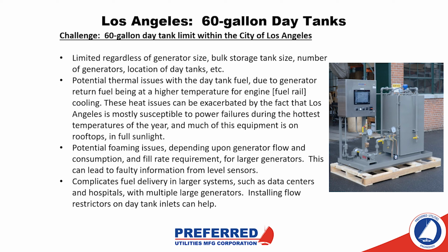So now we're moving on to Los Angeles, and one of the biggest issues that we deal with in LA is the 60-gallon day tank rule. And anybody used to working in the city of Los Angeles on these systems is well aware of this. Basically, the tanks are limited to 60 gallons, regardless of generator size, bulk storage tank size, etc. This is not something that we have been able to get around as far as a rule. We always need to deal with this particular issue. So this is a big one in LA.